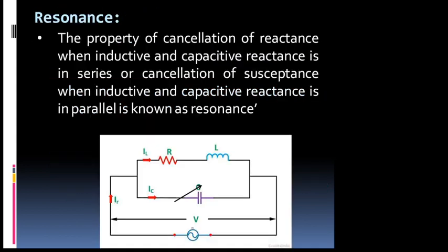One more thing: the LCR circuit is referred to as a tank circuit. It produces a range of frequencies. If the inductive or capacitive value is varying, either or both, then it produces a very wide range of frequencies. The frequency produced by the tank circuit is the natural frequency.